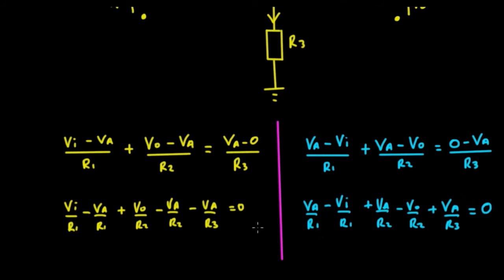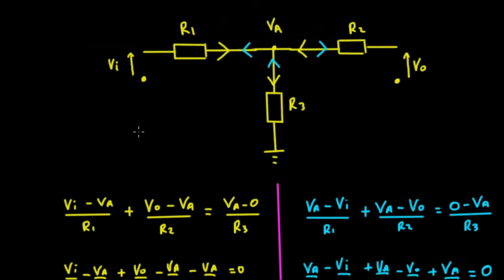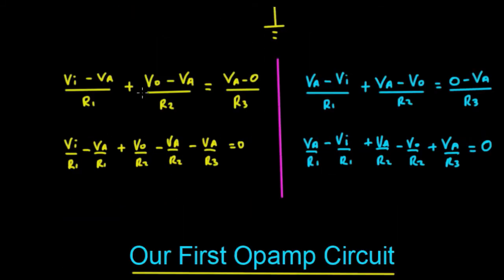So the only thing you need to take out of this really, in order to design these circuits or analyse these circuits, is to ensure that whenever you define the volt drop across a resistor, if you say the voltage from Vin here to VA, it will give you the current in that direction from Vin to VA. So that's the only thing you have to remember there.